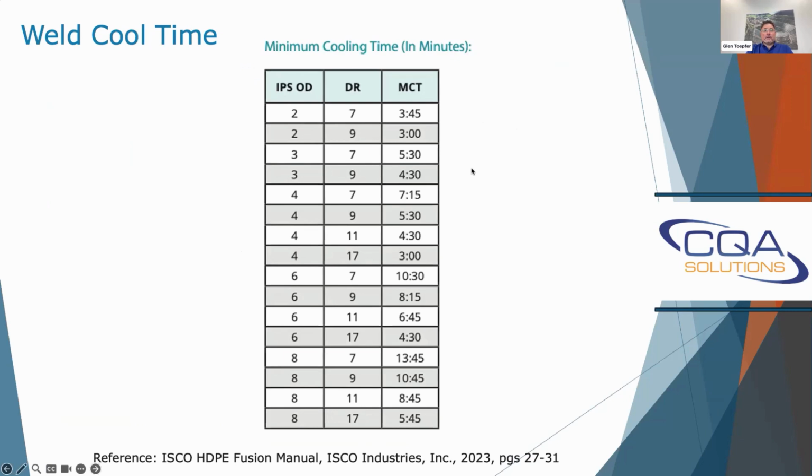And I think that's another consideration for geomembrane installers: there should potentially be a weld cool down time. I don't know how much it applies to fusion welds. I know you wouldn't want to dump any water on them right after you're done welding them, but I know people sometimes will air test them as soon as the seam is done. I don't know if there's any issue with that or not.